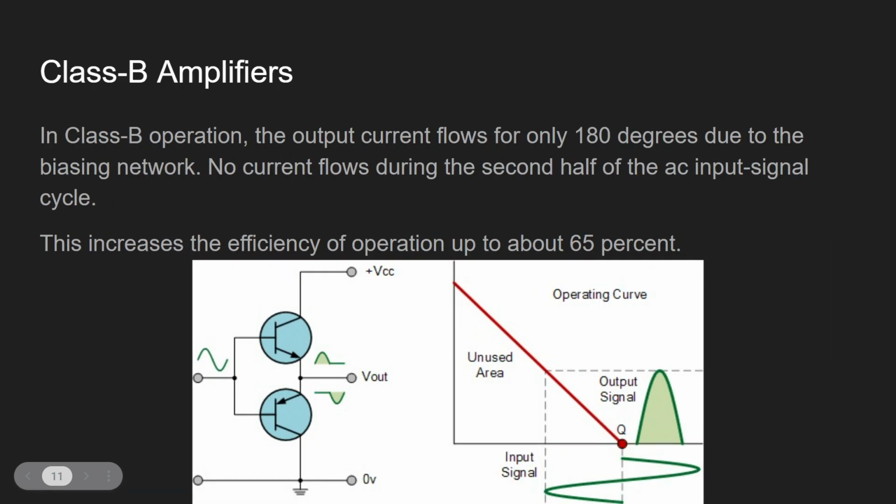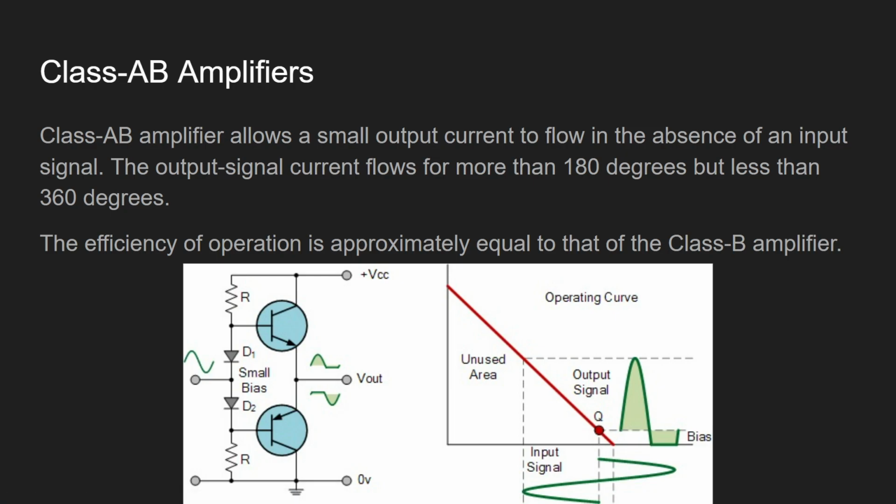If we just use a Class B amplifier, we just have half of the signal, right? So actually it is adding up two signals. It is a flat curve and a flat curve. So actually it is not that smart to use. But for Class AB, it will choose from time to time. If the signal is less than 0, they will switch to another amplifier. So that's why for Class AB amplifiers, we must use both of them at the same time. We must. Okay. So you see that it is slightly larger than 180 degrees, and it is better than using a Class B amplifier alone.